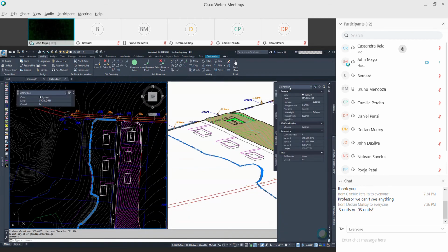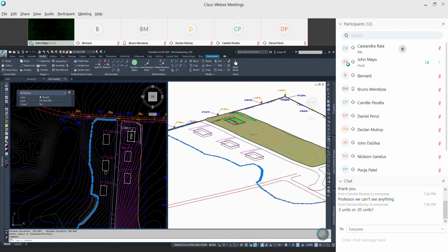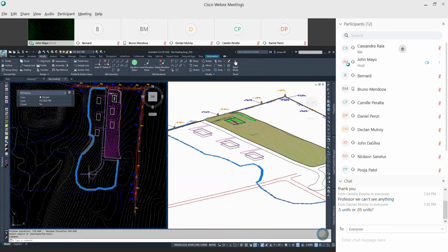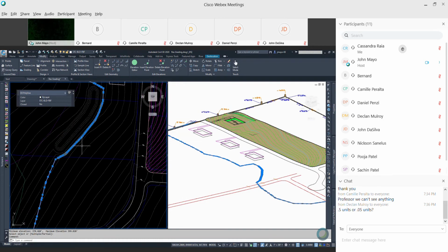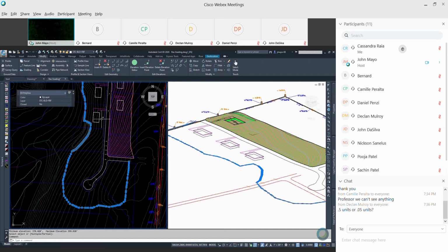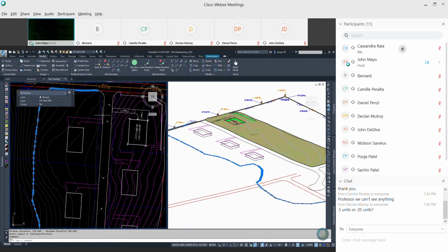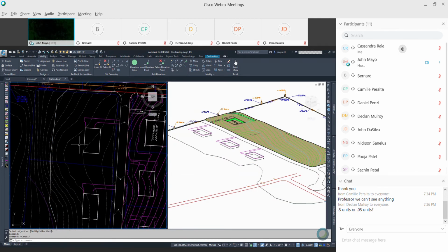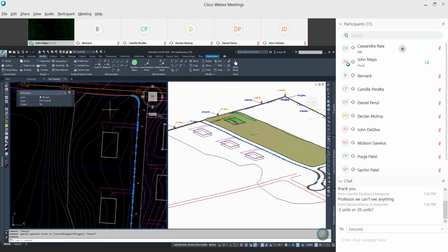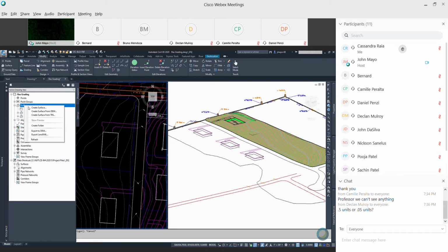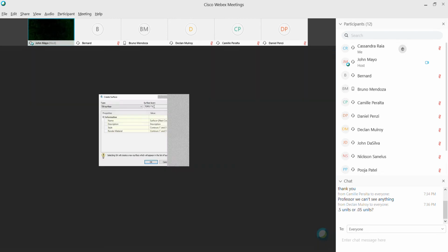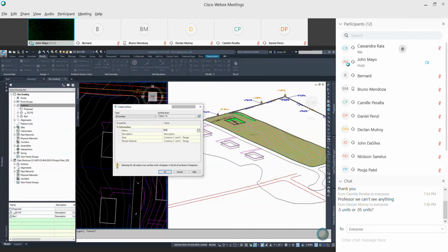And I just show you that because that's going to be a little easier on your computer than a feature line, especially with all these vertices that you want so that the surfaces line up perfectly together. So you can work with feature lines, interior, and keep these as 3D polylines. It'll still work fine. So what I'm going to do is make a new surface. And I'm going to call it Res 2 because I already have Res 1.